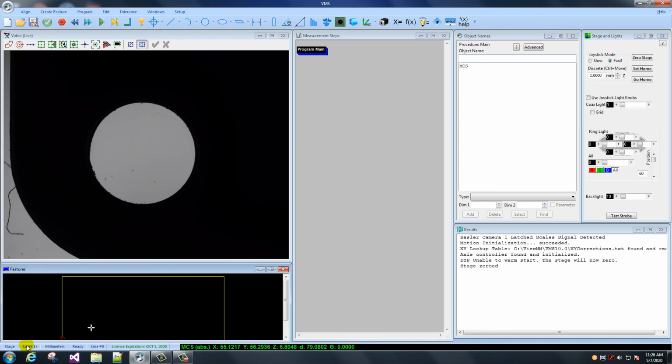The Spark 1X will show you what your lens is. So if you change to a 5X view lens, it'll be view 5X or whatever you name your lens. These are the units that we are currently running in. This says we're ready to go. This is which line is highlighted, and since we don't have any lines, we're at line 0, program main.